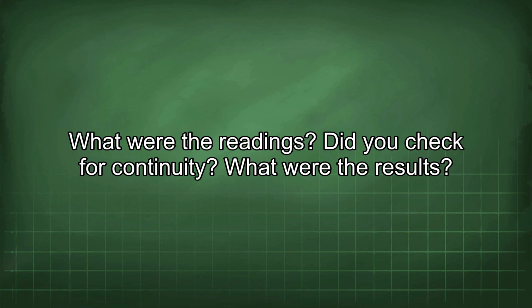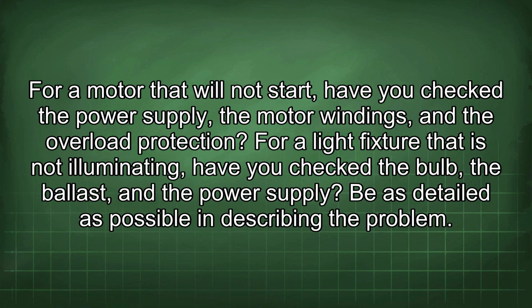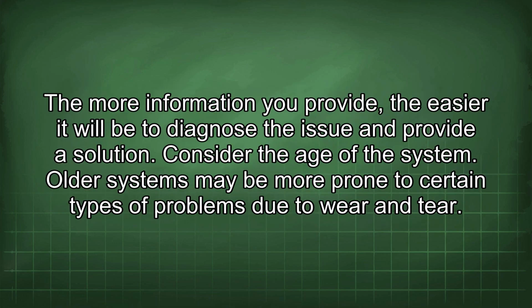What were the results? For a motor that will not start, have you checked the power supply, the motor windings, and the overload protection? For a light fixture that is not illuminating, have you checked the bulb, the ballast, and the power supply? Be as detailed as possible in describing the problem. The more information you provide, the easier it will be to diagnose the issue and provide a solution. Consider the age of the system.